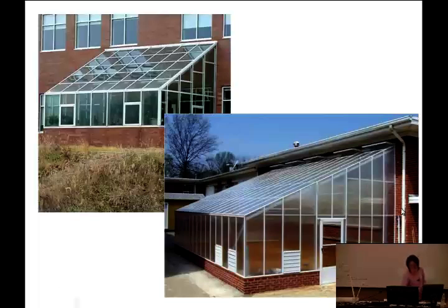However, with south facing, a lot of direct sunlight comes in, but it creates a lot of shadow to the north end because of the diffuse light. Diffuse light is completely blocked there. Direct light is basically from the south side, but diffuse light is all over, right? So if something is sitting right here, this side is not receiving diffuse light coming from behind the building. That is reducing the radiation.